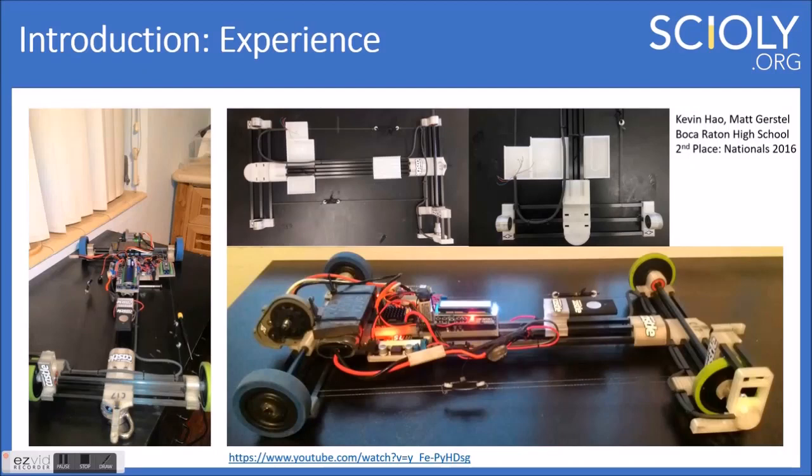We have a third Arduino that was used as the master communicator, so both the other two Arduinos were feeding information to it. So this one was like the master control center, and it also outputted signals to the ESC to control the brushless motor, as well as taking in information from the rotary encoder and the LCD screen and compiling and processing that information.